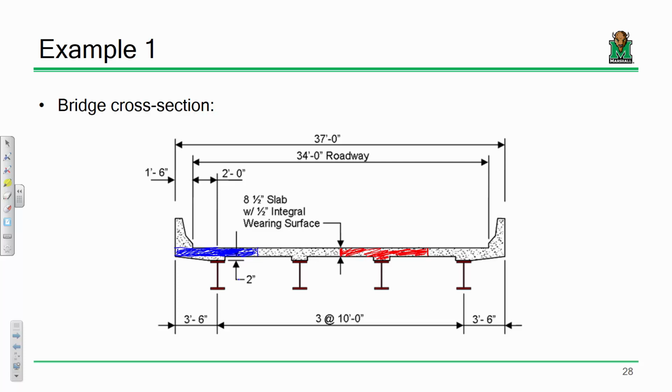Now, which beam do you think is stronger, the exterior or the interior? Interior. How wide? What is this dimension going to be? 10 feet or 120 inches? Is that going to be 10 feet? No, it's going to be like 8'6", right? So this has less concrete helping it out than this one. Okay, everybody okay with that?